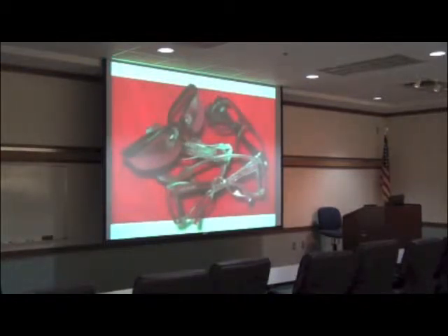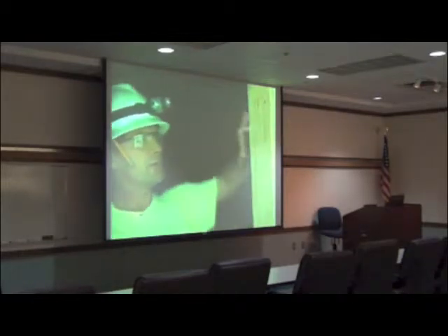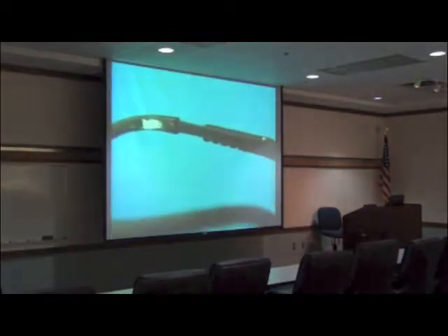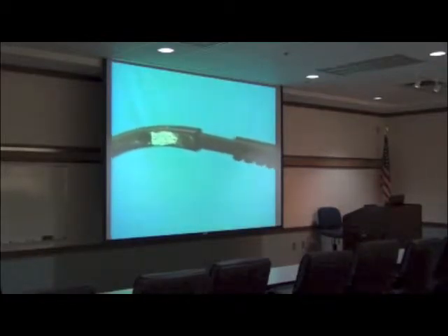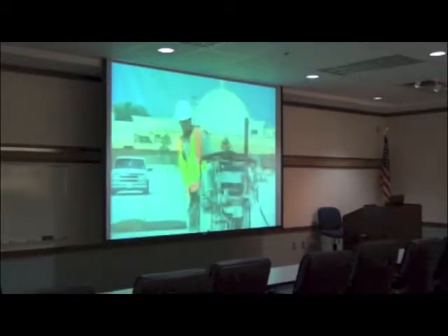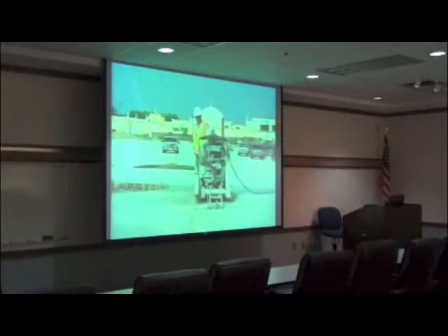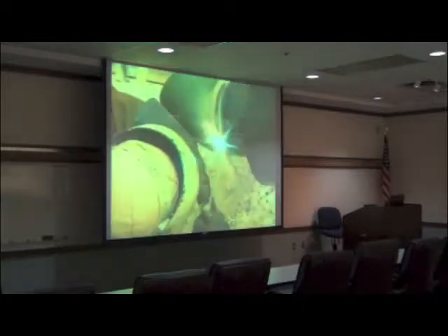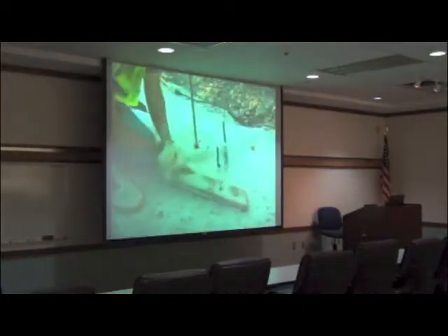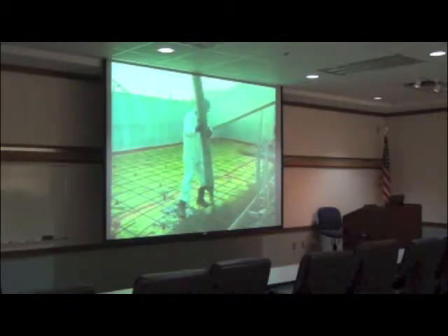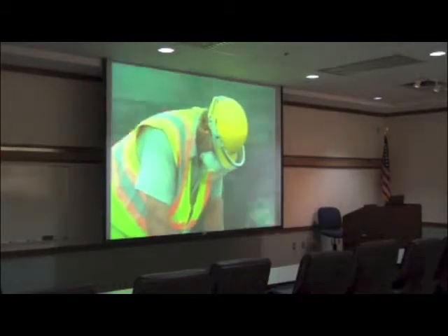optical radiation hazards. You will know that your safety glasses have been rated for construction hazards if they have been stamped with the Z87.1 designation. In general, wear safety glasses or face shields anytime there is a risk of foreign objects or substances getting into the eye, such as during welding, cutting, grinding, nailing, or when working with concrete and/or harmful chemicals, or when exposed to flying particles.